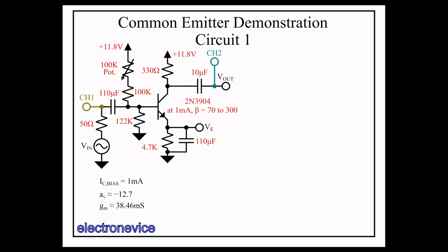Note that since we're going to be taking our V-in measurement after the 50 ohm resistance, the actual source resistance, Rs, of this circuit amplifier is 0 ohms, not 50 ohms, though this will have very little impact because 50 ohms was pretty small to begin with.